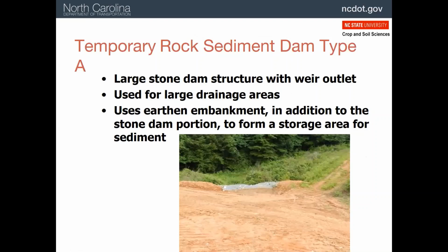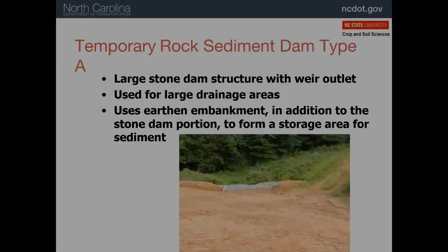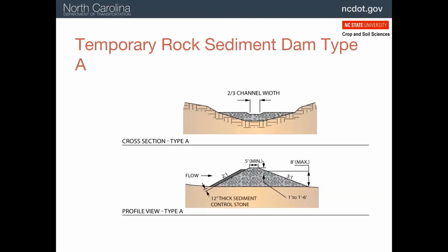Now basins sometimes are the old type with the rock and the stone as an outlet. And here's the front and cutaway views. You can see some of the details where we have the large rock, a weir cut in it, and then the face of 57 stone washed gravel, at least a foot thick. So what does that do? You should know by now it slows the flow through the rock and pools the water.